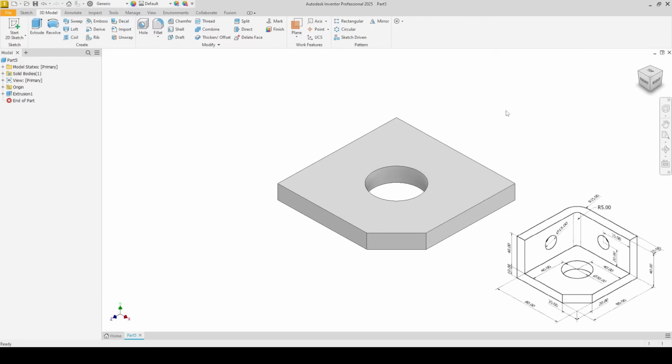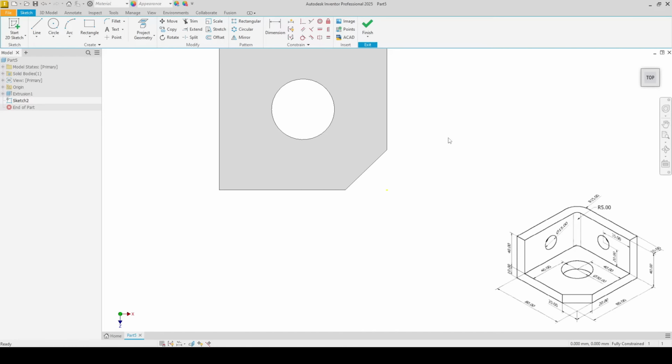So for these sidewalls, nice and easy. First of all, we need to define the plane in which these sidewalls will extrude from. In this case, it's this plane here. So different ways of doing this, but what we can do is left click. We've got a series of options here to edit that feature, which we don't want to do. We do want to create a sketch on this plane though. So let's click create sketch.